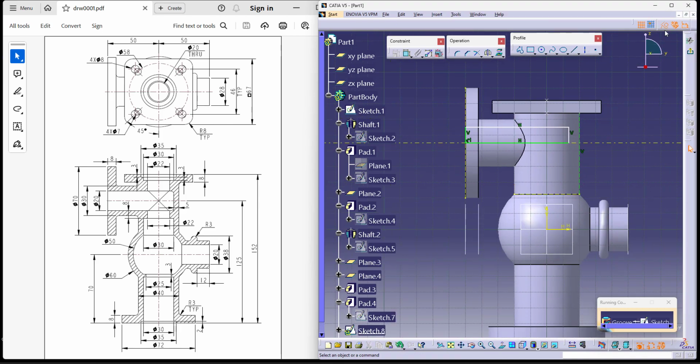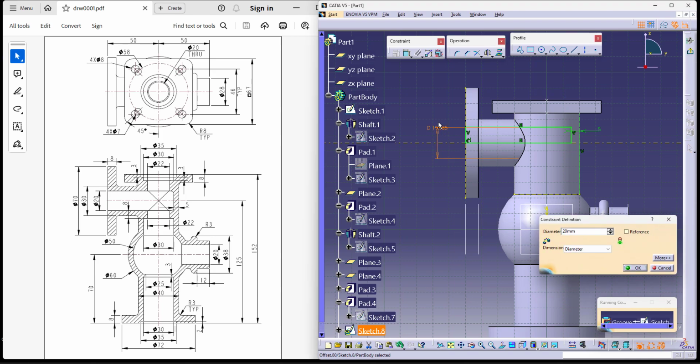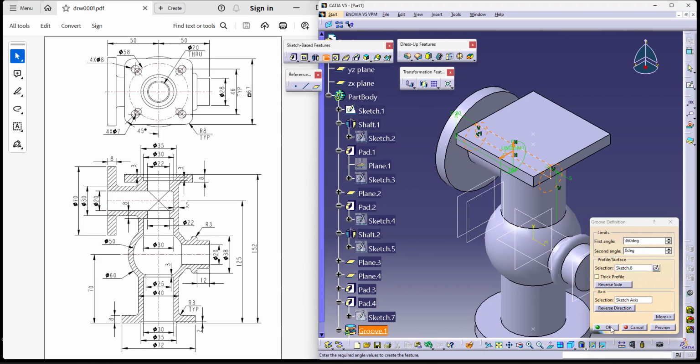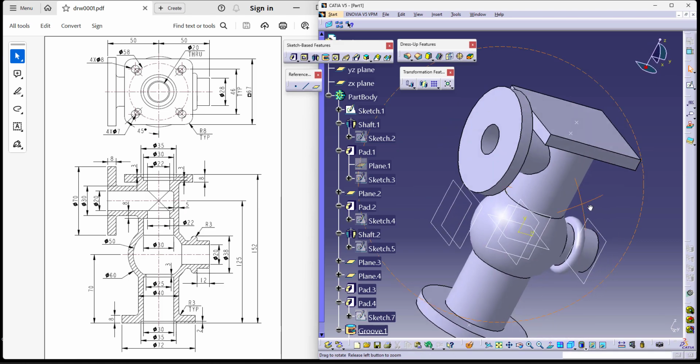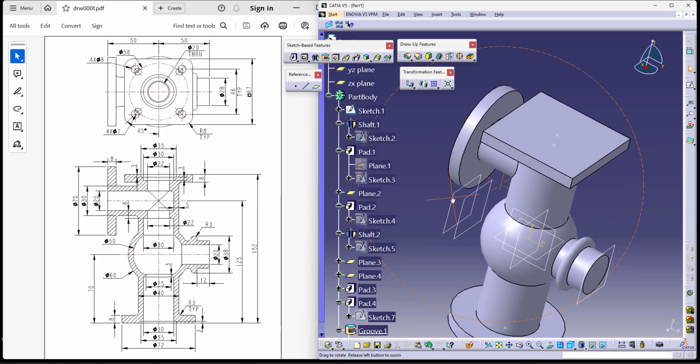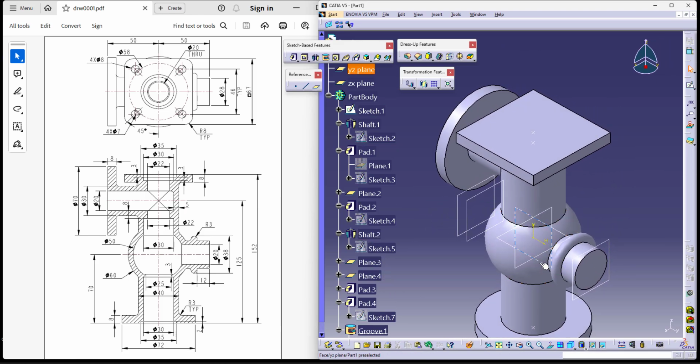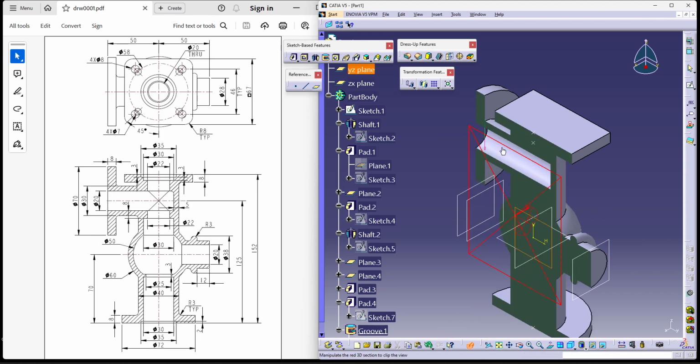Now I can start giving my dimensions in a better way. The distance from here to here is supposed to be 5, and the diameter it is supposed to maintain is 20. So let's take that as 20. While doing so, we can always use a diametrical sectional cut and also work on it. As you can see, this will be your cut. From the internal cuts now, if I have to show you the internal cuts, this is the front internal cut as you can see.